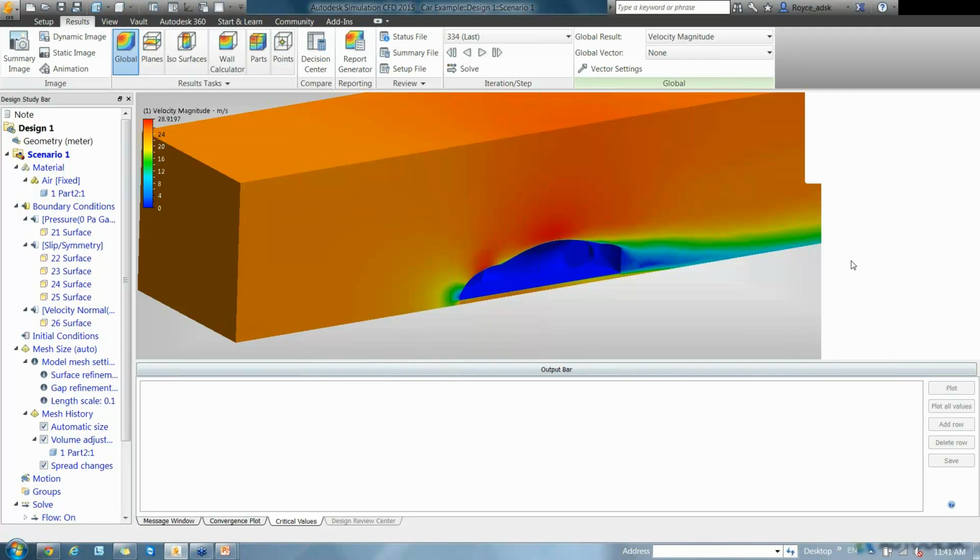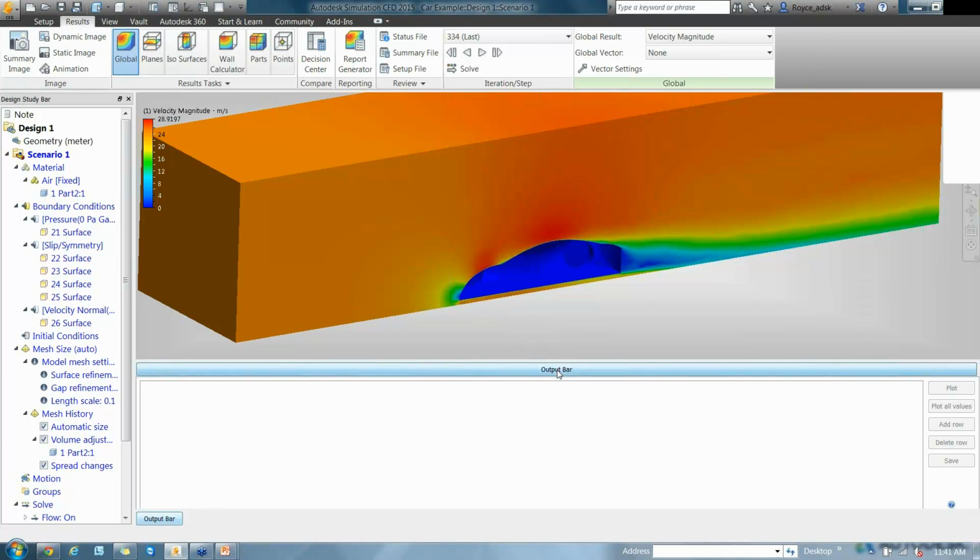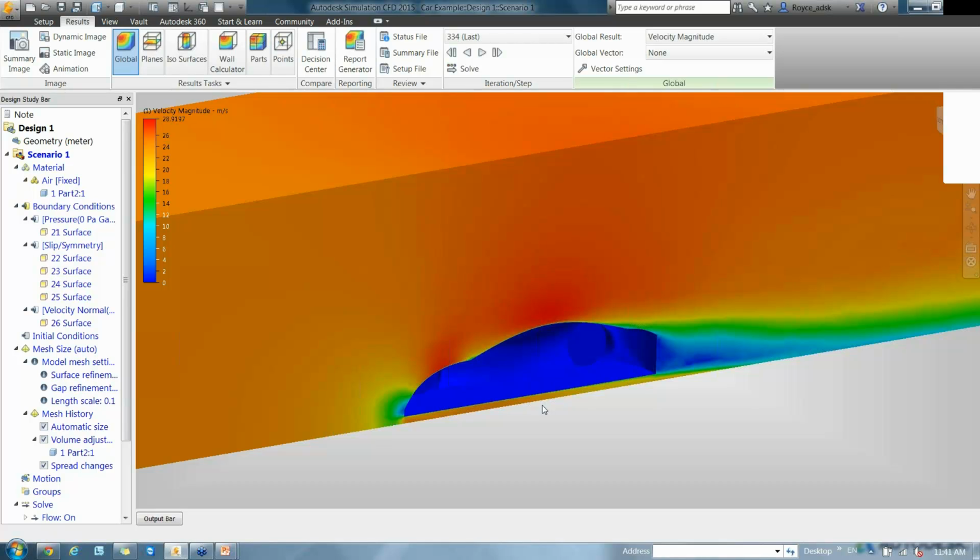And then one other is if you wanted to actually go into what the Y plus value actually meant. So what is a Y plus? Basically, it relates the velocity at the first node away from the wall and how that velocity should be compared to the expected boundary layer profile.